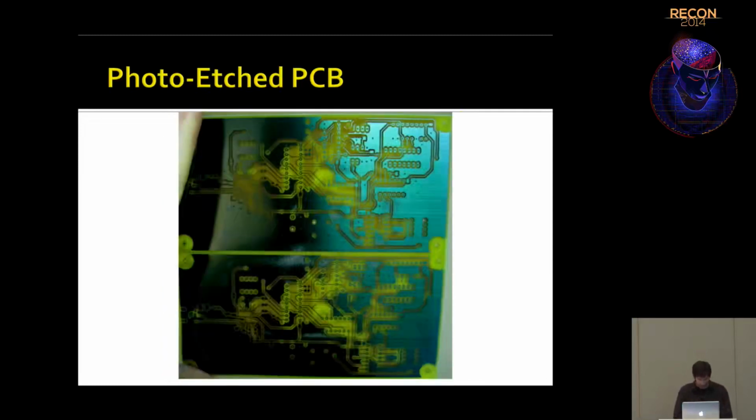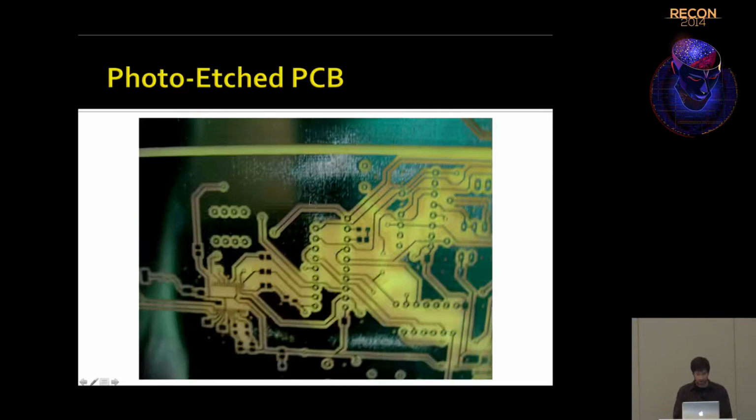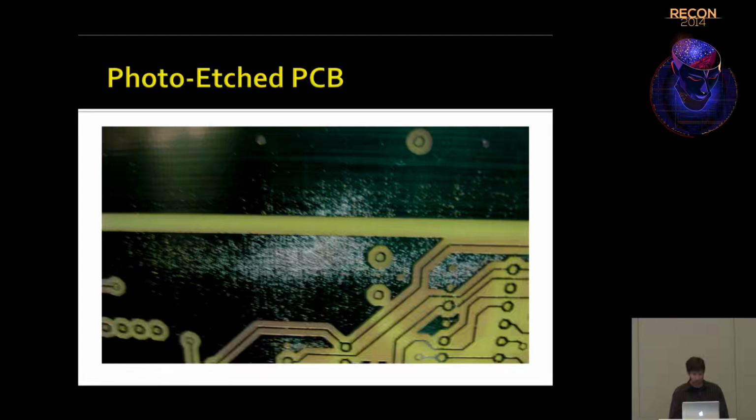You can see there's big, well, it's hard to see in this area, but there are chunks here that are totally etched through unevenly. There are traces missing all up in here. Dimitri heard me whining about my epic fails with this, I think. Areas here where it's already starting to eat through the resist of what was supposed to be a ground plane. Closer area there, which looks disastrous.